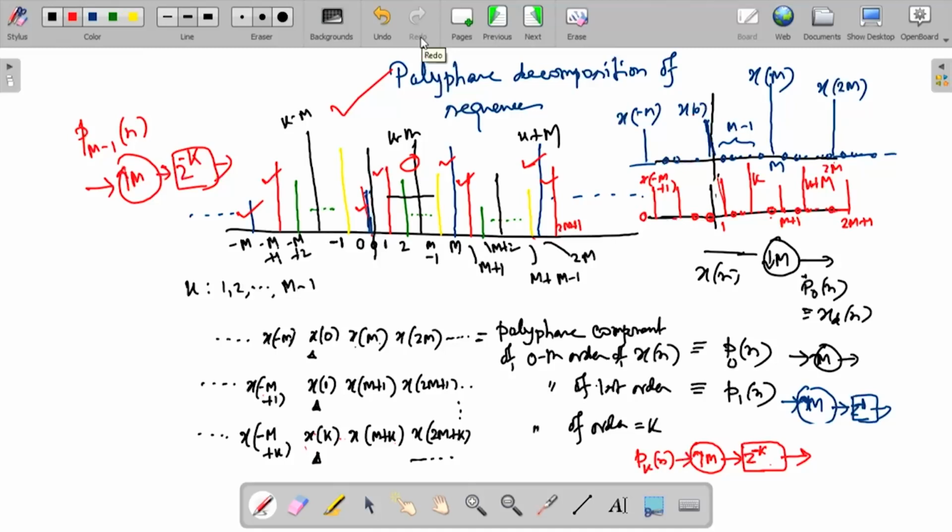All right. Yes, very easily, you just take various such figures, P 0, P 1, expand, that is insert zeros, m minus 1 number of zeros between every pair of samples, shifted to the right by appropriate number of indices, like if it is k, p k n, like this sequence, expand, that is insert m minus 1 zeros between every pair of samples here, then shifted to the right by k.